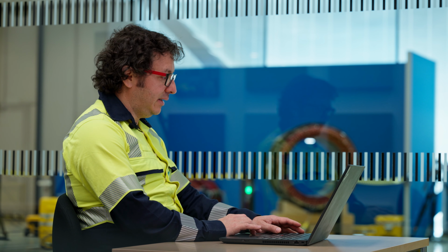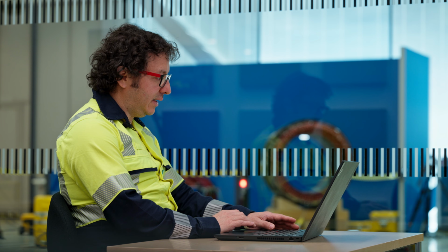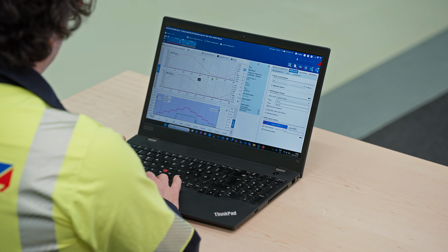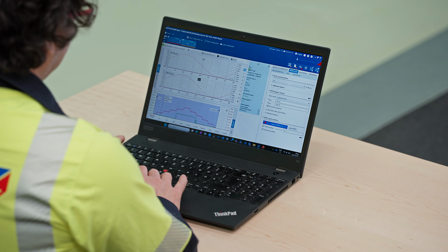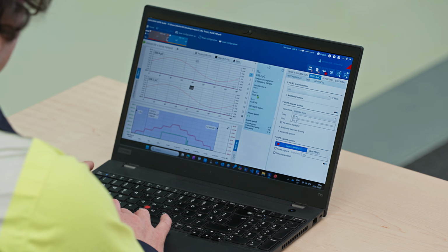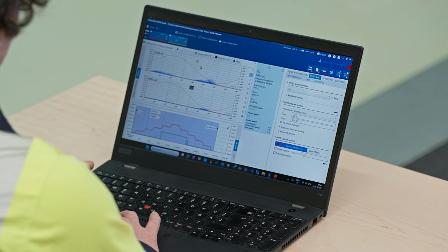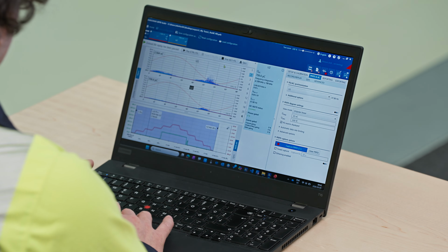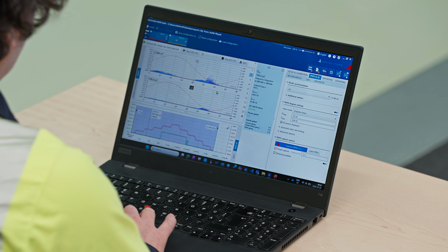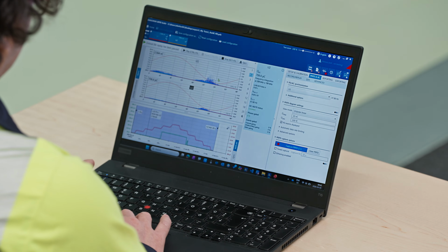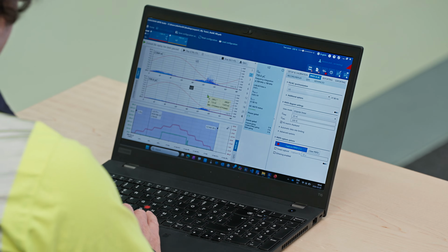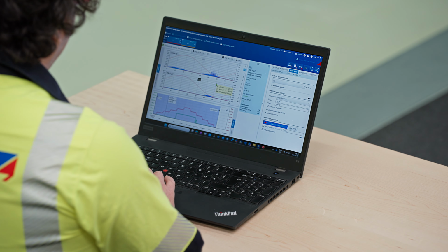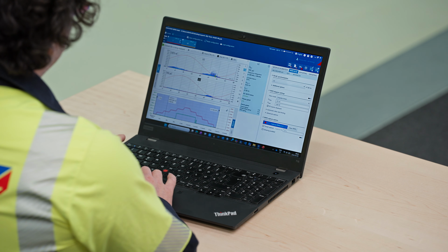I'll replay the data set. While the data set is replayed, we see what the charge is that is measured. We also see the test voltage here. We also can click on pause, and then we can take a close look at the PRPD in order to determine which type of PRPD pattern is developing. We can continue with the measurement,